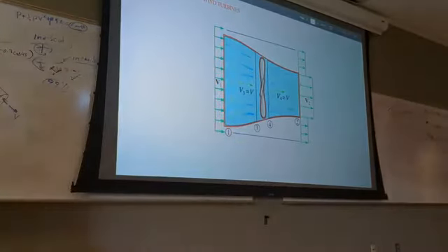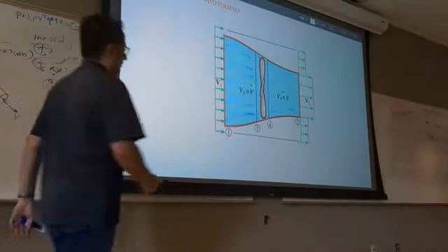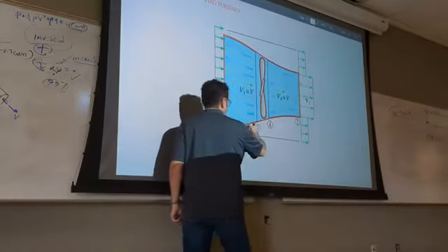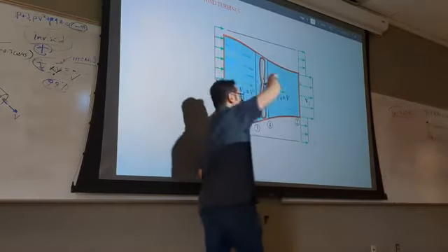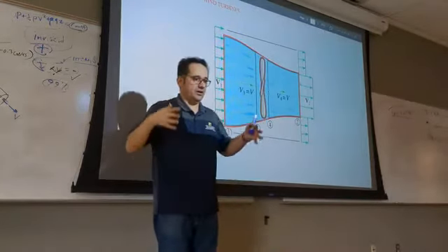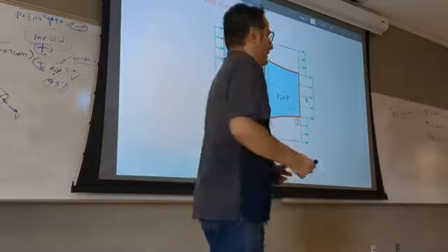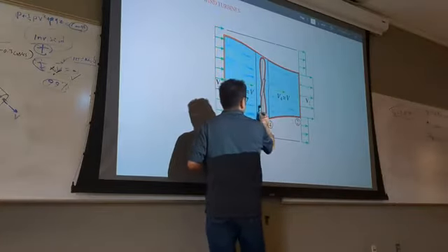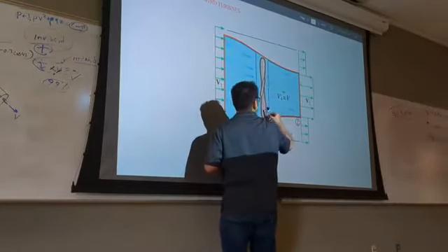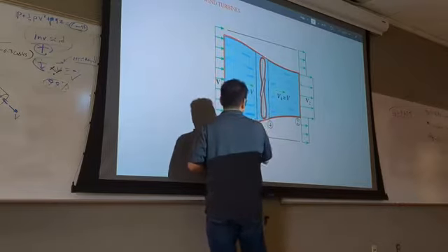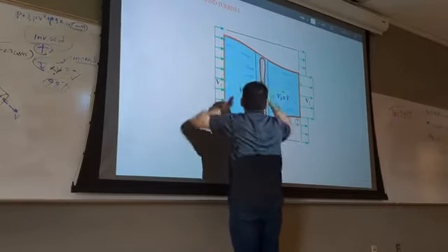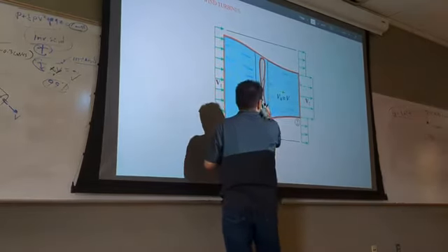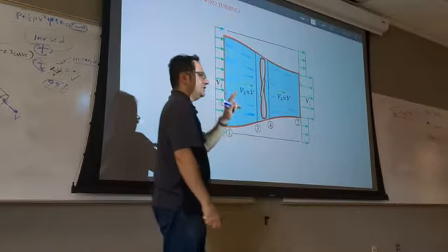We took a control volume that is adjusting to the airflow. So the velocity, you see this is a streamline, so the velocity is tangent to the outer boundary of the control volume. If you look at it in 3D, that's just like a tube. And it's surrounded everywhere, but we also exclude this object, this prop. So we have one control volume from here to here, and one control volume from here to here. And the third control volume is between here and here. So we have 3 control volumes.